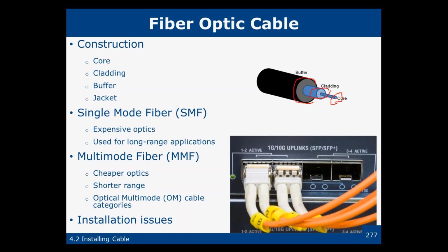But when you make these things, you strip off the cladding and it shows, and then you put it into a connector, and they usually have 4 or 5 connectors that they want you to identify also. You polish the end to get it smooth, put it in the connector, and then you basically glue it in and polish it so that it makes contact with the other end.